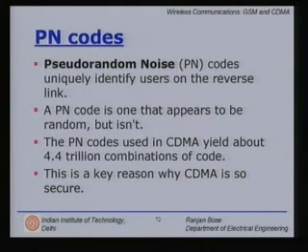So if your phone is on but is in the standby mode, then your code can be given to somebody else. Okay? So a code is not fixed or locked. Also, when you move from one base station to another, then you may have to switch between codes. Right? So my mobile is given a code during the transaction. When I call, my code is also transmitted as a signal to the receiver side.